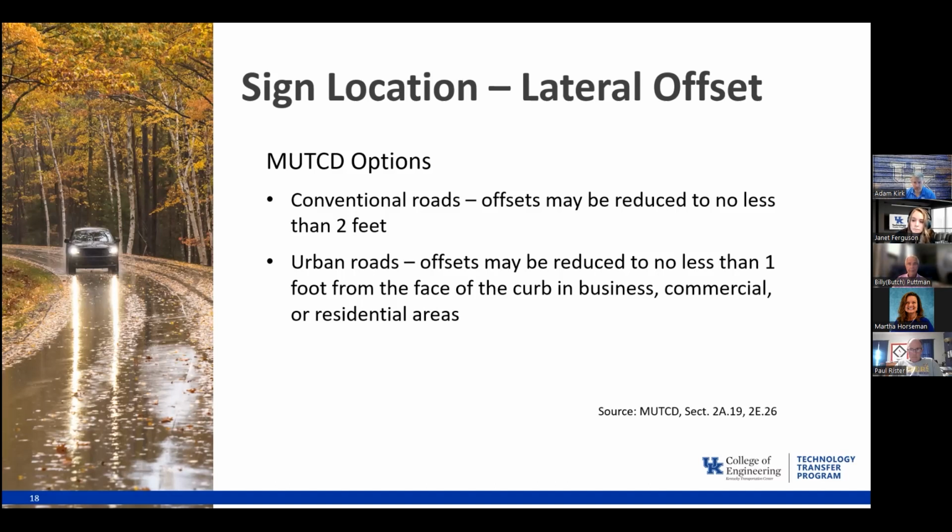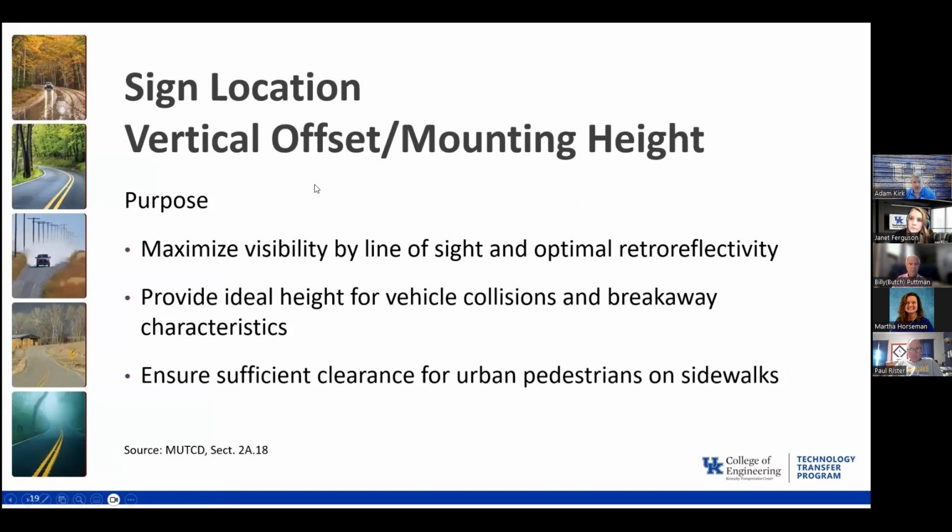So, basically as much room as we can, up to that 12 feet, but recognizing that we're not going to have that kind of right of way. We're not going to have that kind of placement option. So we can reduce that to 2 feet in rural areas and then 1 foot in our urban. The next thing that I want to talk about is looking at how high does that sign need to be,